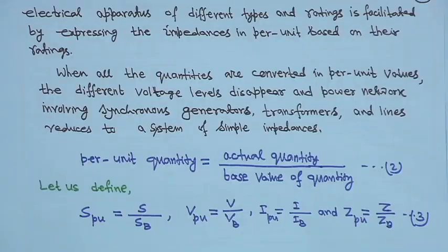Then we will come to the downstream, the distribution system. So, instead of mentioning all these voltage levels, if you choose an appropriate base and all the voltages are accordingly transformed, then the different voltage levels will disappear from your circuit diagram. This is a major advantage, right. So, all these things can be represented by simple impedances, right.